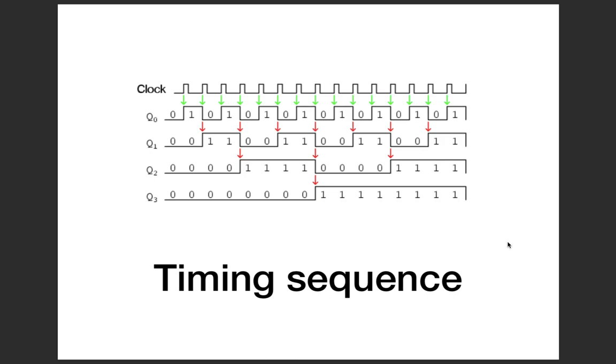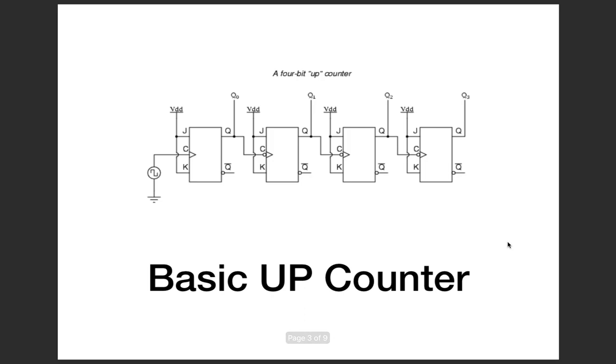So we built the circuit for that. We used T flip-flops because it was a toggle operation all the time. There was no particular additional operation to do. So today we will see it once again based on a JK flip-flop. One very important feature of JK when compared to T is that T is a particular kind of flip-flop where J and K are short-circuited.